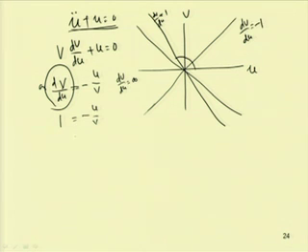Now one can draw several lines. On this curve draw several equispaced lines with slope dv by du equal to 1. By drawing several lines with slope equal to 1, it will make 45 degrees with the u axis.